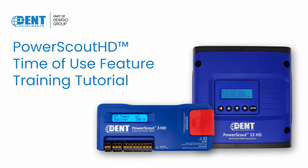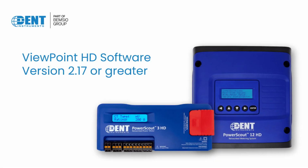Welcome to the Time of Use tutorial for the Dent Instruments PowerScout HD Series submeter. The Time of Use feature is a premium feature available for the PS3 and PS12 models and requires Viewpoint HD software version 2.17. The Time of Use feature can be used to configure 3 separate tariffs to track accumulated kWh and peak kW according to a defined schedule.